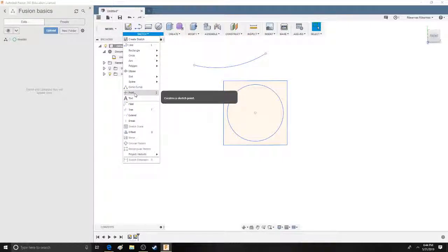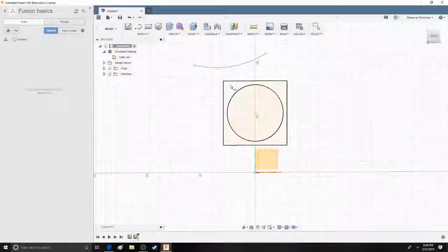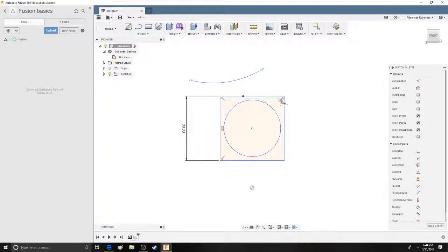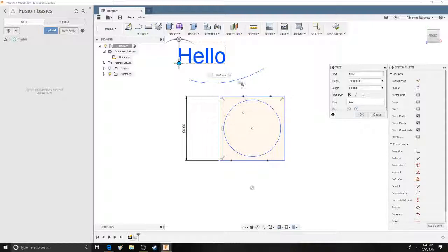And then right below that, you can create a sketch point just by adding a single point on it. This is good for measurements, especially if you're like, I want to know the difference between here and here. You can add a point right there. So you can connect those 2 or just have them for reference. And text, which is fairly straightforward, place a single location right here that you can drag around with your keyboard or mouse. And you can add text right onto it, and this will function just as a sketch.